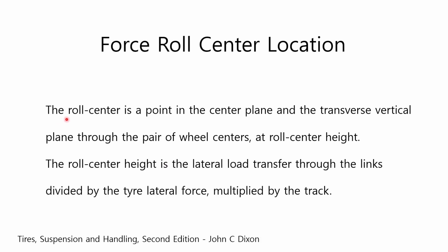Combining the information discussed so far, the location of the roll center can be defined as follows. The roll center is a point in the center plane and the transverse vertical plane through the pair of wheel centers at roll center height. The roll center height is the lateral load transfer through the links divided by the tire lateral force, multiplied by the track. You can find this definition in John Dixon's book, Tires, Suspension and Handling, 2nd edition.